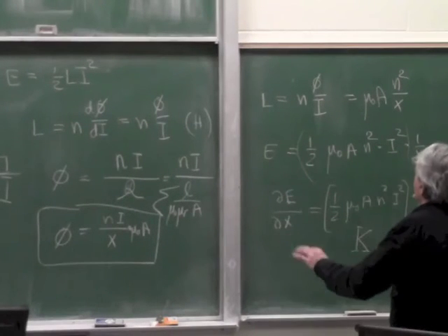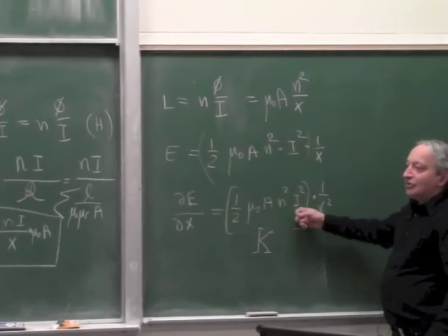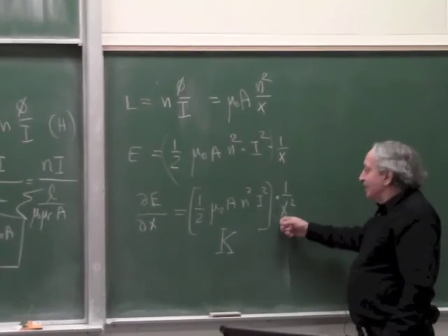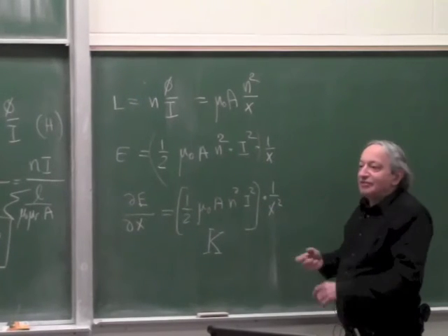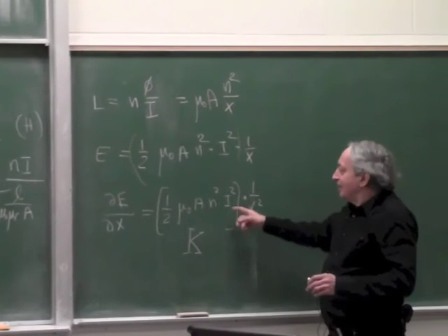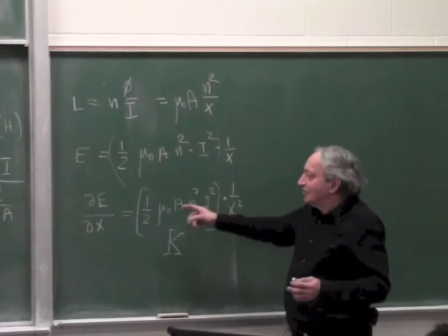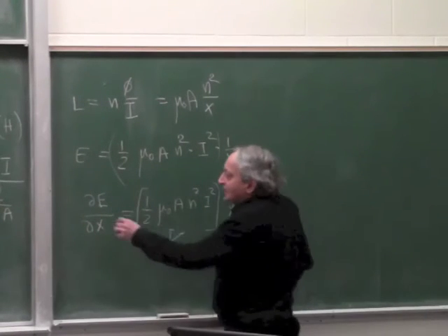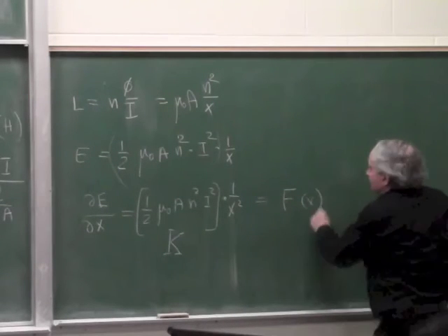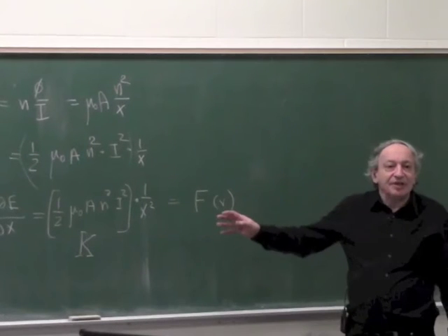Okay, so these systems are nonlinear with control current. Both things are actually bad, because both things mean variable gain. Gain depends on position, and gain depends on the drive current. Because you double the drive current, the force goes up 4 times. Because this is actually F, right? This is a force as a function of x. Okay, so is the derivation completely clear?